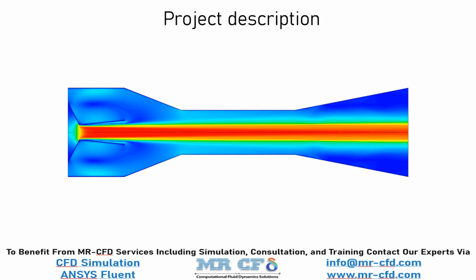In this project, two-phase flow of vapor and liquid ammonia in a two-phase ejector has been simulated by ANSYS Fluent software. The realizable k-epsilon model is used for flow analysis. The VOF multiphase model for two phases of liquid and vapor ammonia has been used to investigate the phase interaction. The energy equation is also activated in this analysis. The liquid ammonia will enter the computational domain through the primary inlet with the pressure of 9 megapascals and a temperature of 393 Kelvin. This flow will induce the vapor ammonia to exit the ejector along with liquid ammonia.